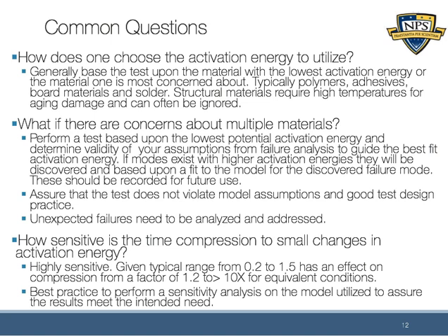So the question becomes, which one's going to be limiting? And of course, it would take a little bit of work, and you might have to be more of an expert to be able to do this quickly. But essentially, if all the other test parameters are the same, the lowest activation energy will cause the first failure. So if you're going to be looking for a failure mechanism in a part, you'd want to go with the material with the lowest activation energy.